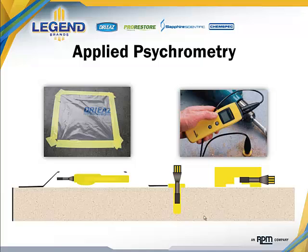And believe it or not, the measurements that we're talking about can be much simpler than this. The containment, the holes, etc., are not necessary when you're evaluating airflow. All you need to do is simply place the hygrometer on the surface of the building material and allow the hygrometer sensing element to measure the moisture at that surface.